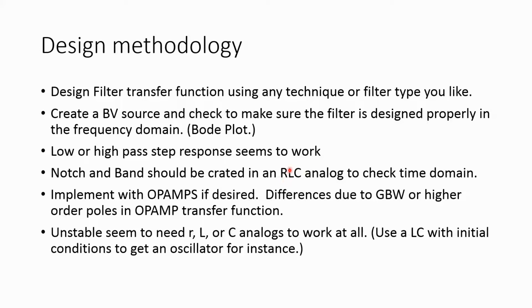So it's probably better to make an RLC analog of the filter you want to check in the time domain. Now that doesn't mean you're going to make an RLC filter. You're just trying to simulate the time domain response of a second order notch or band. How it ultimately gets implemented is a different story.